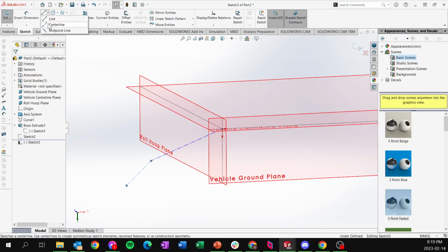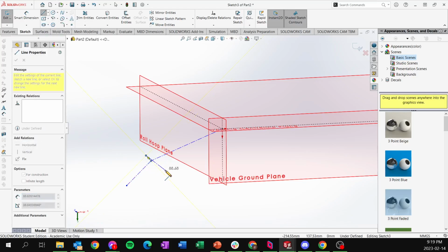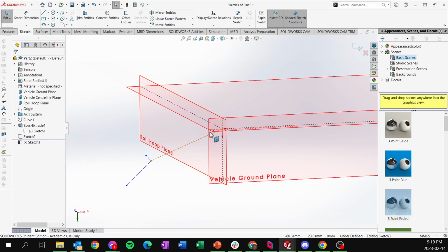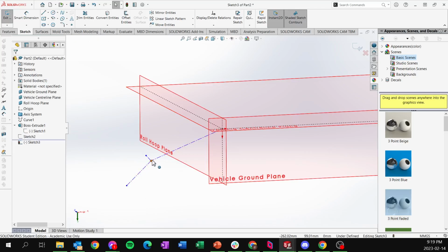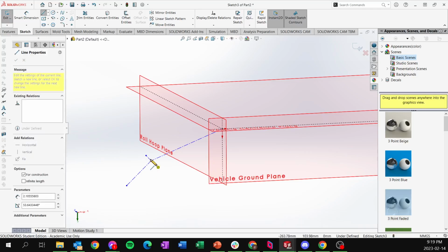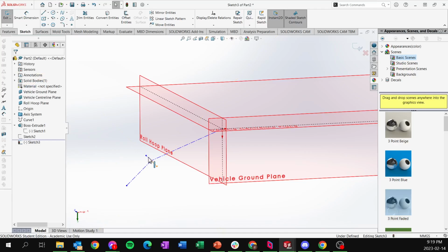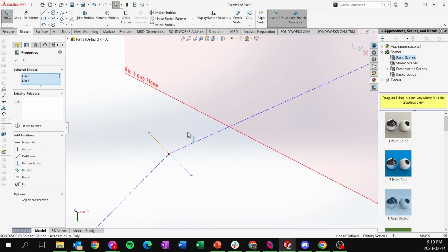Basically, you create your trailing edge right here, and this is going to be your leading edge. And then right here, where I'm sketching this little thing, basically the camber, this is where the max camber is going to be, so I'm going to make those equal.